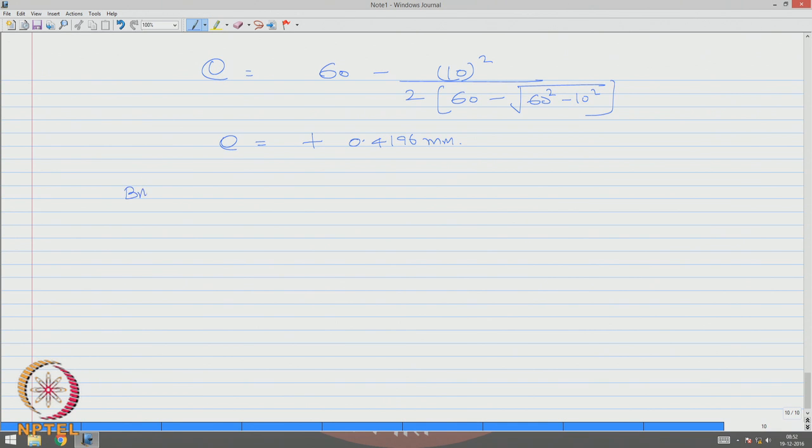So, we also know bending moment at any angle theta is given by Mb is equal to PR by pi, pi by 2 minus 1, minus PR by 2 (1 minus cos theta). So, let us say at section BB we understand that theta is 0.